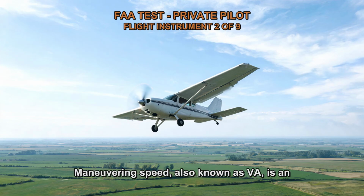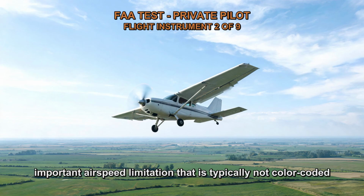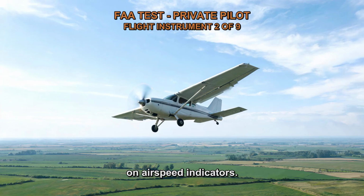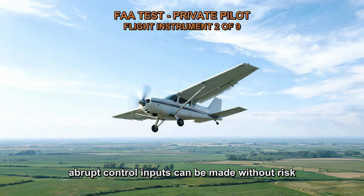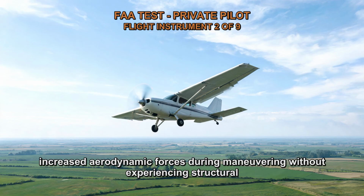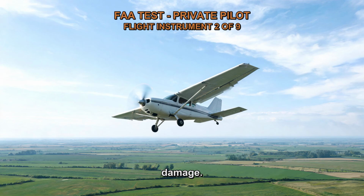Maneuvering speed, also known as VA, is an important airspeed limitation that is typically not color-coded on airspeed indicators. Maneuvering speed is the maximum speed at which abrupt control inputs can be made without risk of exceeding the aircraft's structural limitations. It ensures that the aircraft can withstand the increased aerodynamic forces during maneuvering without experiencing structural damage.